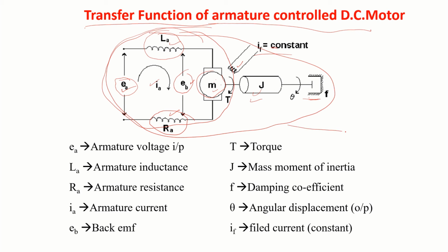When the current I passes through the motor, a magnetic field is produced around the coil. When this coil rotates, it cuts its own magnetic field, which induces an EMF that opposes the incoming EMF. This we call back EMF.